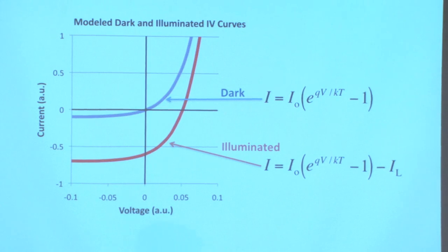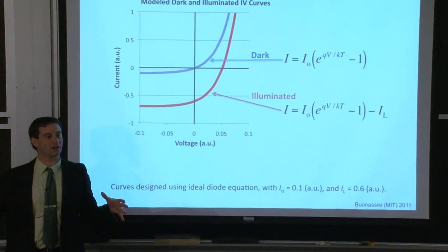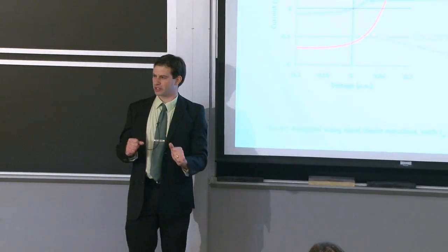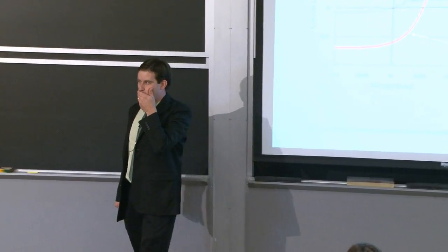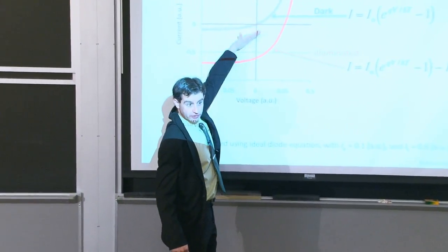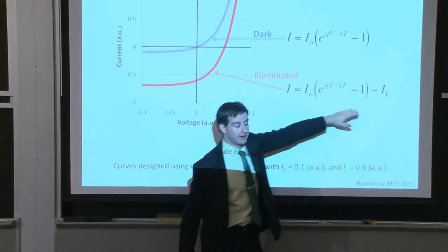All right. What do we think will happen if our light intensity goes down by a factor of 2? So now if the amount of sunlight falling on our solar cell drops by a half, what will happen? What do we predict will happen based on this right here? The red curve will shift up by about half, right? Because the illumination current is now cut in half.